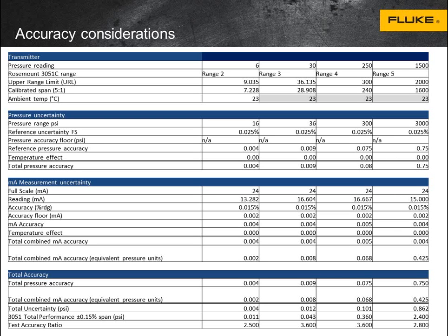The one thing to keep in mind is that because the TAR doesn't take into account a lot of the sources of uncertainty that a TUR does, a TAR is almost always better than what you'll actually see in the field. So again, remember we were saying that 4 to 1 is kind of the standard, although in the field 3 to 1 or 2 to 1 is more common. The graphs I'm about to show you are actually not as good as they appear.